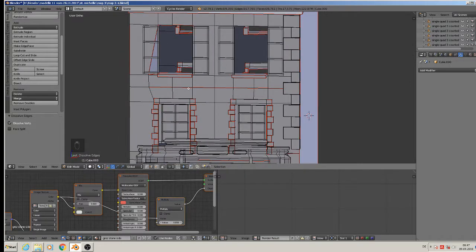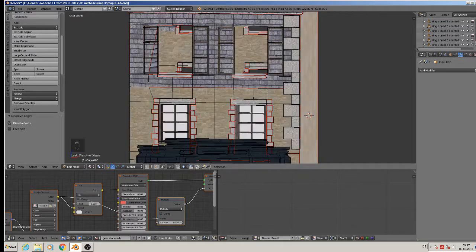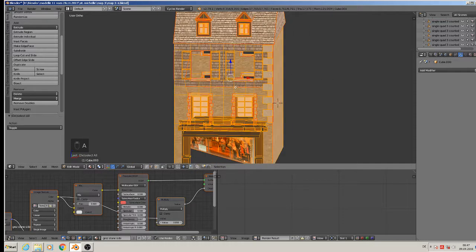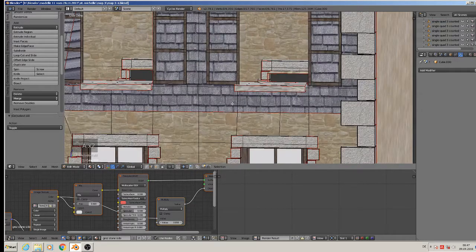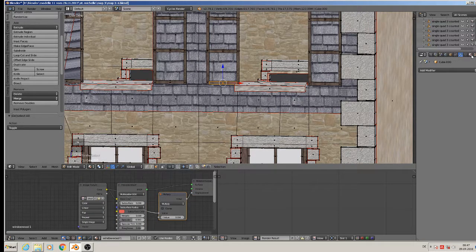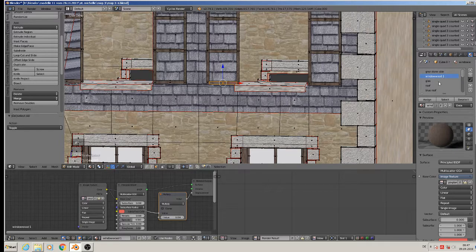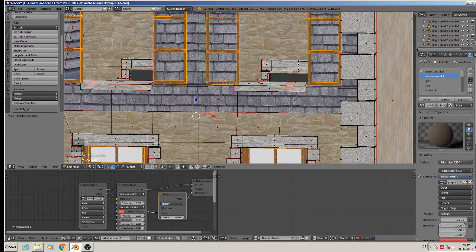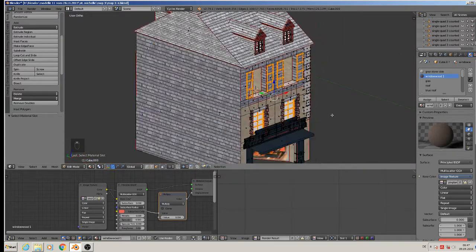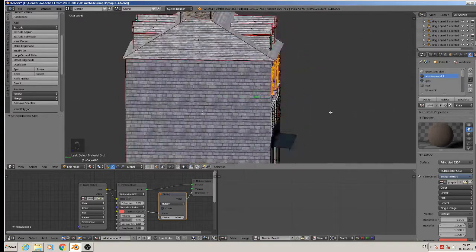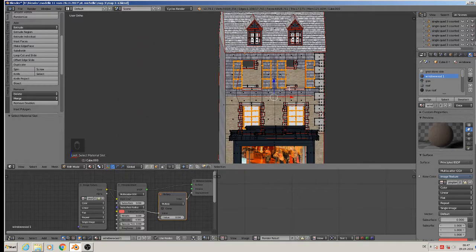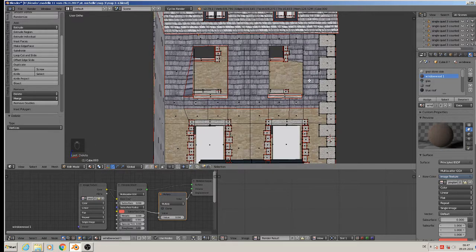Okay, at first we go back to material mode. We want to delete the windows. The windows all have one color, so we click here. And we see it's Winwood. So we say here select Winwood, and it selects all that is done with this Winwood. So we can delete them simply. X delete vertices. It's gone.